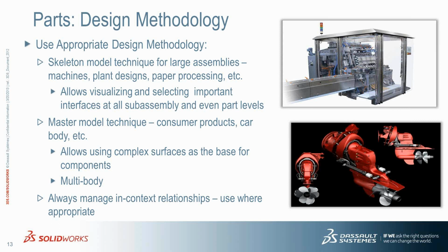Now there are other techniques, like using master models, inserting a part into a part and using that as your start part, or skeleton modeling, where you start at the assembly level with layouts and blocks and create all your parts and assemblies referencing this sketch and layout. All of these are appropriate as long as the geometry warrants it. You want to think a little bit about what method is best in this case.